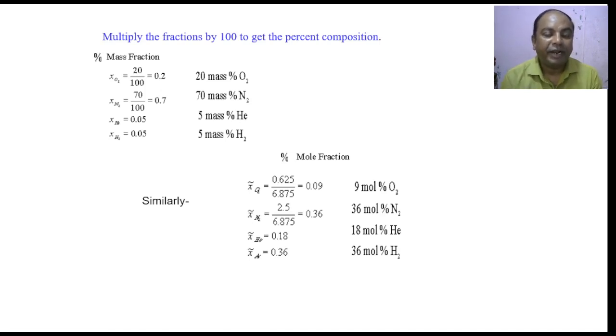So the streams entering the unit process may be given in different units. Some may be given in moles, some in mass, or some in kgs. Then we have to make one unit for the material balance calculation, that is, either in mole or in kg.